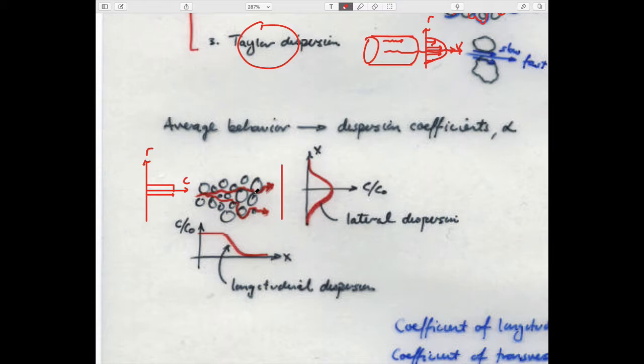You know, they go further, the flow paths diverge, and it moves laterally from here. And longitudinal dispersion is that if you draw a section along here from A to A prime, then you'd expect that the high concentrations due to this go to lower concentrations here at the front. And so there are two effects.